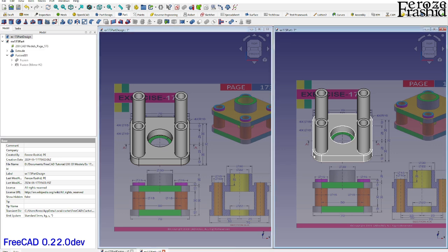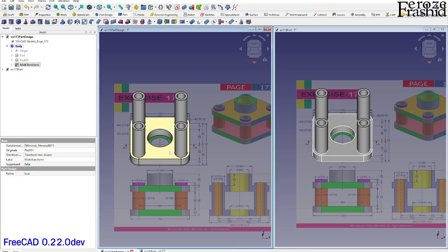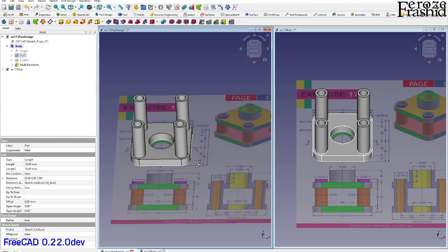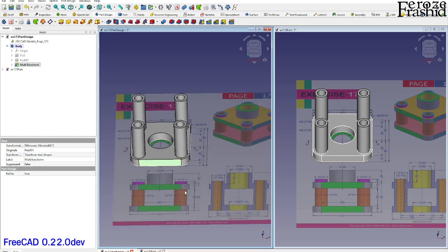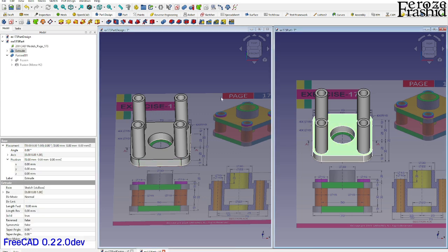The next thing, we can go ahead and take this one, place it 40 millimeters above, and I think we can copy and paste it, we can clone it. So I'm going to go ahead and do it clone on part design. Okay, so the next thing is to place this pad 40 millimeter above from the base, and we can do that easily in part.